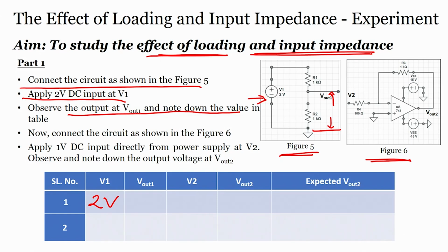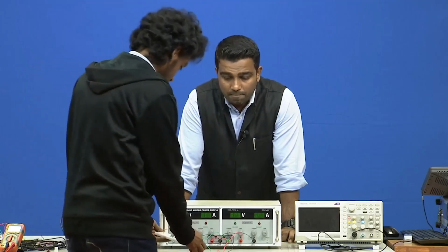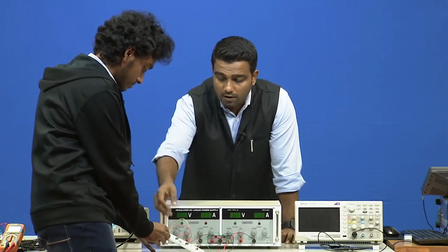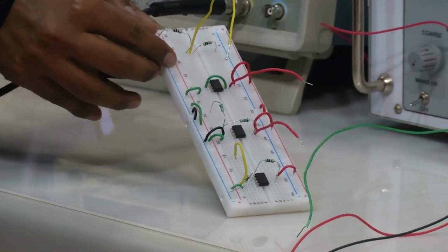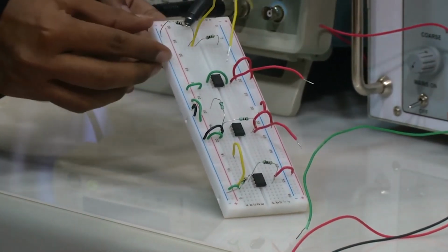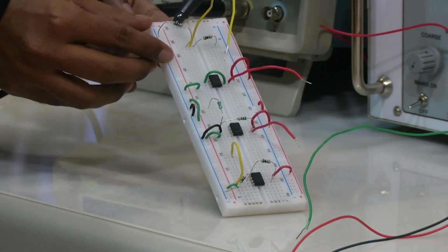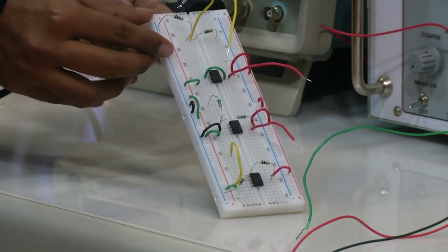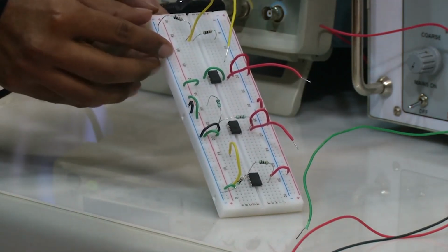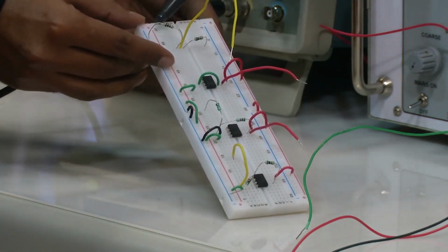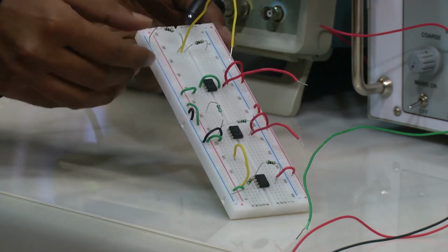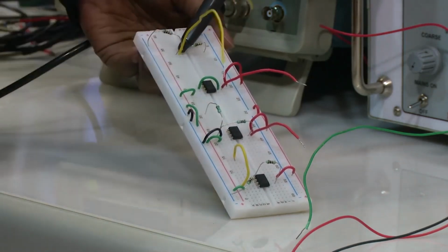So, now you see the voltage divider circuit right over here, which is the first one, alright. The first one that he is holding here, these are 2 resistors, right, connected in series, and now we will apply voltage, which is your input voltage, across these resistors, and we will measure the output voltage across resistor R2, alright.